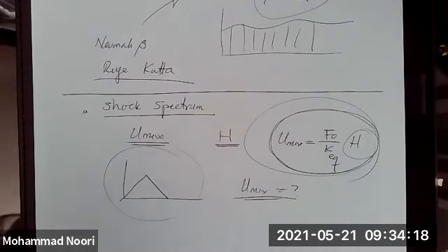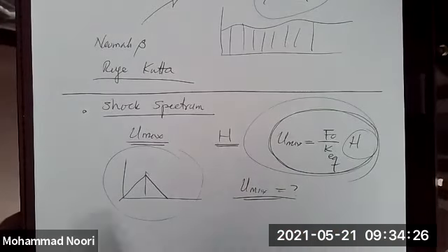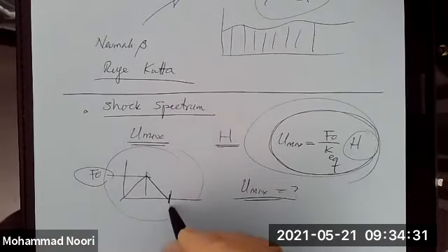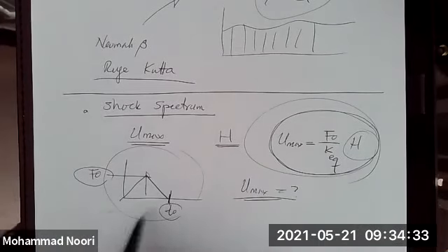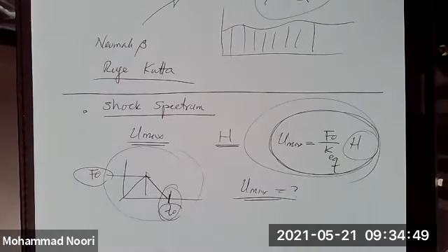In these cases, when you have general loading like this, the maximum displacement depends, as you saw, for instance, when we solved this problem, not only on the magnitude of the load, but also on the time duration. So it is important if we can come up with an approach that, depending on what this time duration would be, you can find the maximum response as a function of that.